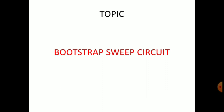In the last class, we have seen different sweep circuits and sweep voltage. We have seen the definition of sweep voltage, and we have also seen the voltage sweep circuit and current sweep circuit, depending on RC or RL, and we have drawn the waveforms also. How we get the sweep voltage: the restoration time TR must be 0. Then, if it is 0, it will become a sawtooth wave or ramp wave. Remember all those things. Now, quickly moving on to the topic, the bootstrap sweep circuit.